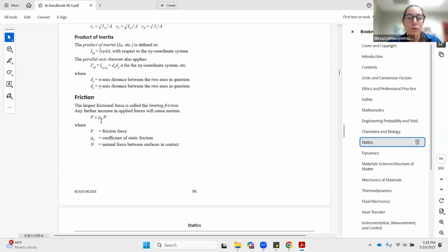external forces. So for example, if you have a block on a plane and the plane is a little bit tilted and the block is sitting on the plane but it's not sliding, then we know that the friction force is going to be less than or equal to the weight of the block part that's pushing down the plane. So that is actually just a maximum that the friction force could possibly be. It doesn't mean that it's necessarily that much, because friction will never be more than the amount that is required to be, because friction will never push something in the opposite direction. Like, it will never make it move in the opposite direction.